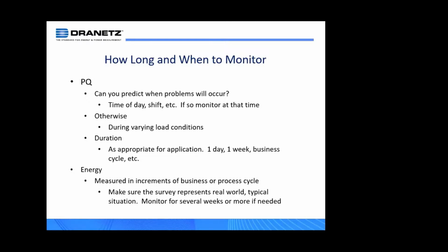Let's say today is the 22nd, 23rd. So you put the instrument on the 23rd at 11:50 a.m. and you're going to leave the instrument there for a week. Typically, what we see for power quality monitors, it'll be a week for PQ. Might be a little bit longer, but the average usually turns out about a week.